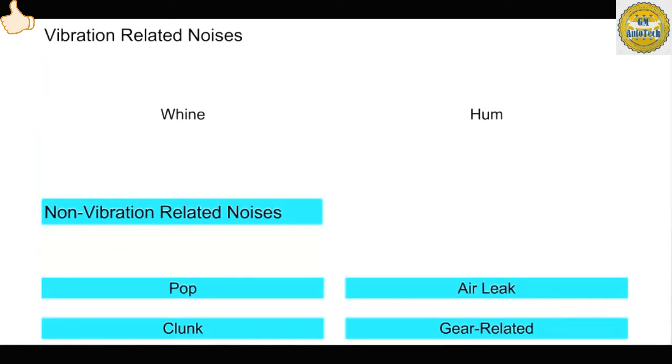There are vibration analyzer tools at our disposal that quickly detect vibration frequencies. This data is then used to pinpoint the source of the vibration and noise. Other noises, however, present a challenge because they often don't last long enough for a frequency to be detected, or the frequency may not match any of the known originators. There are an entirely different set of tools that we use to diagnose these concerns.